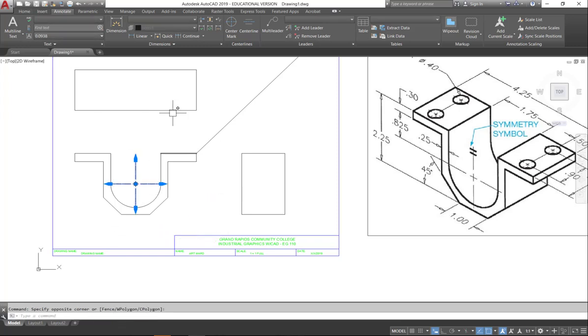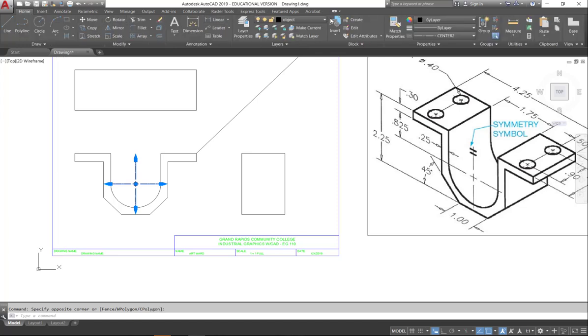I want to change that to layer center, dim sen. So I have part of my drawing left. So I don't have my holes shown here. I've got these 4 holes, but I'll see those in the top view. Let's now start projecting up to the top view.